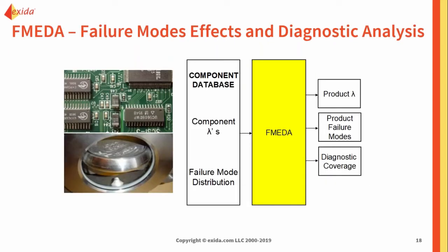When the FMEDA is done, we get a bill of material and a drawing of the device, and we look at every single way we can possibly break each component. We look at all of the stress levels of that specific design with that specific application and environment.